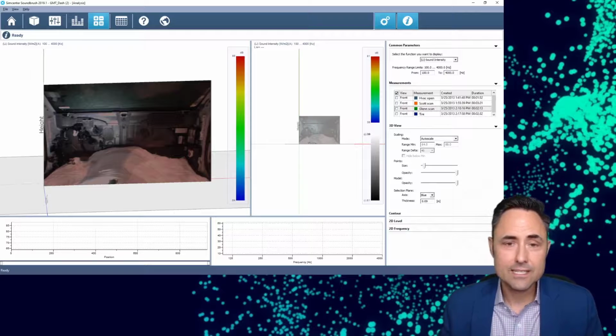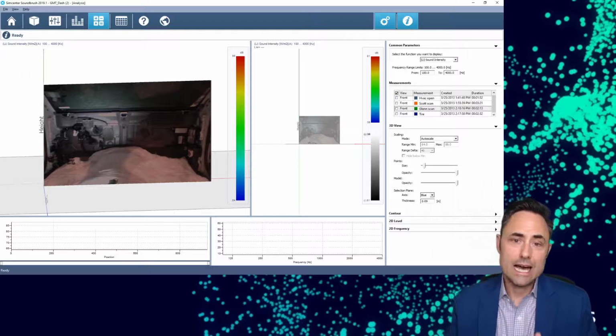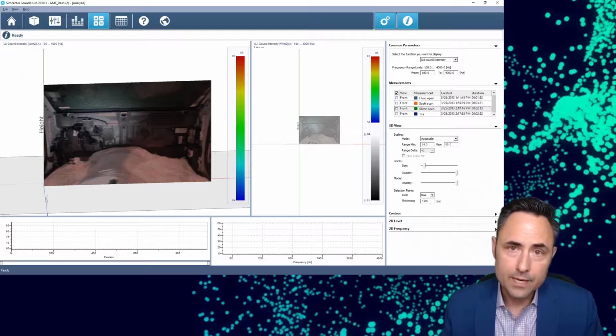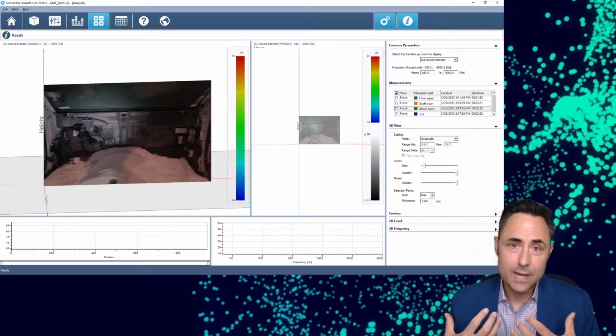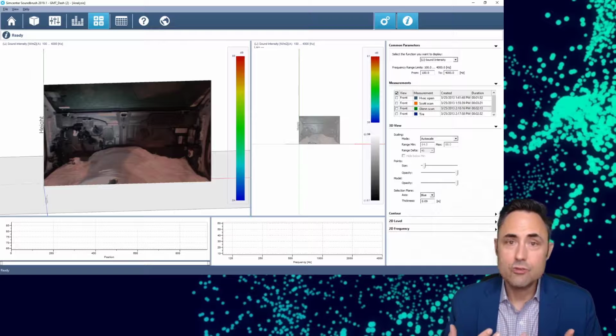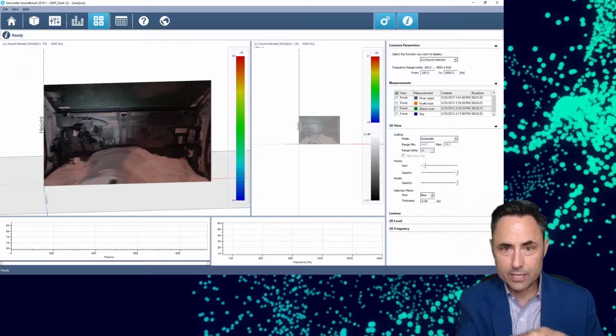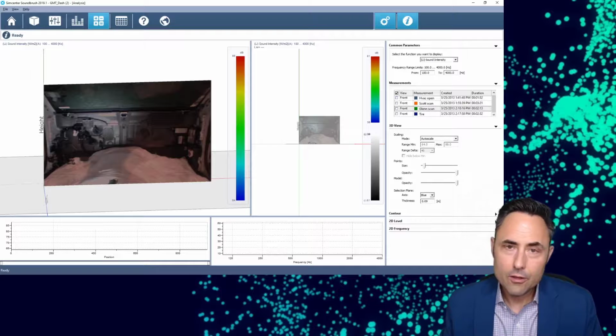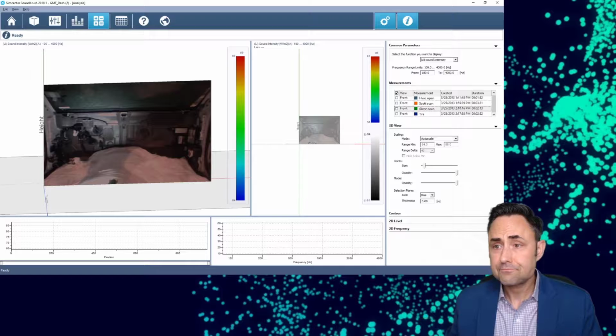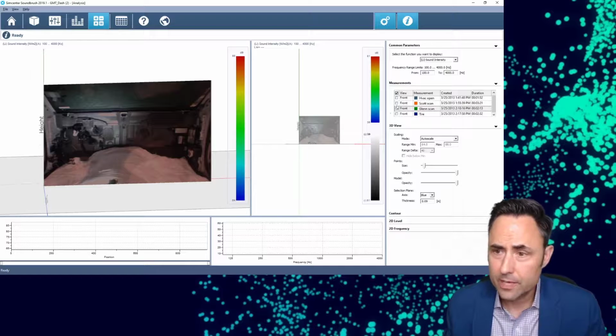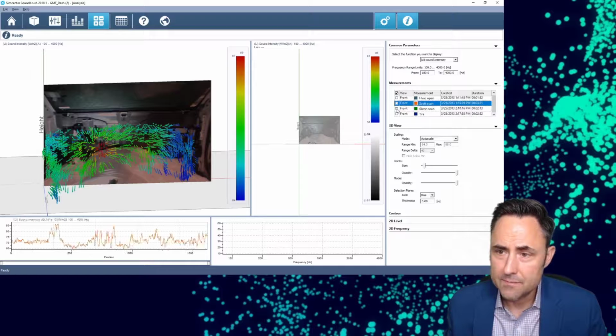And so to test this, we can put a broadband frequency source that's really loud in that front compartment and then measure the sound on the passenger side of that front of dash, right? And you could do this with an intensity probe, and you could set up a grid and measure really carefully the XY plane there and measure your sound intensity. But we did this really, really quickly with the SoundBrush, and I'll put these measurements in here.